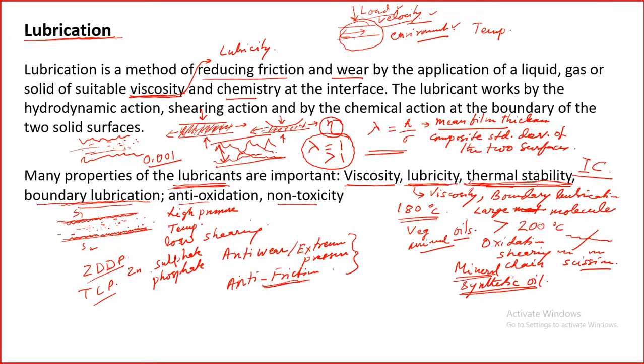It acts in all lubricants. So this basically ensures that these two solids never touch each other. So even under extreme pressure or any kind of situation, let's say this surface comes very close to this, but still this boundary film will separate them, so they will not touch each other and wear will be avoided. So this is extremely important. In all oils they have this one, anti-wear and extreme pressure.